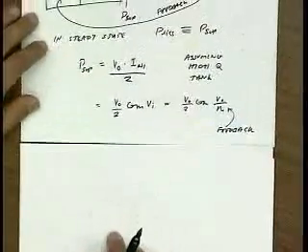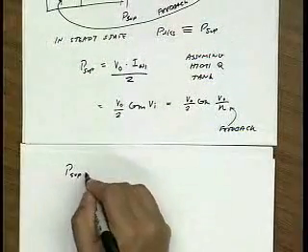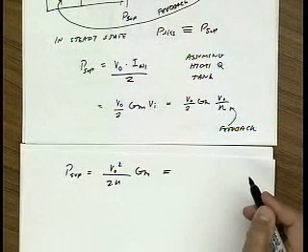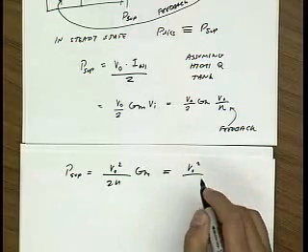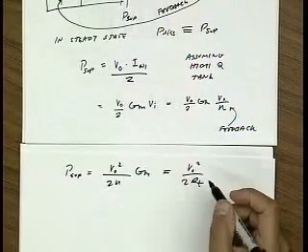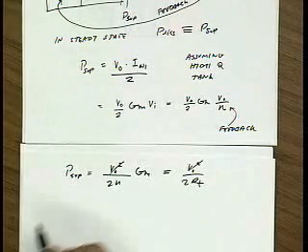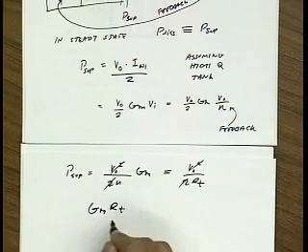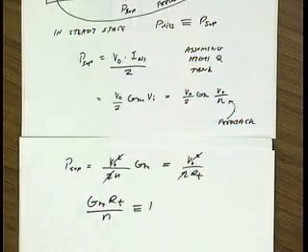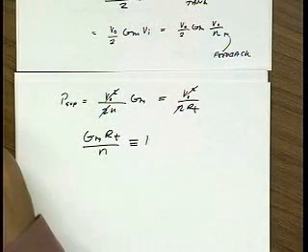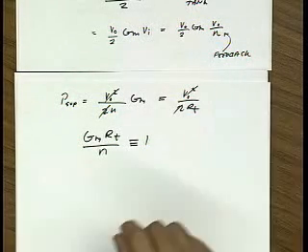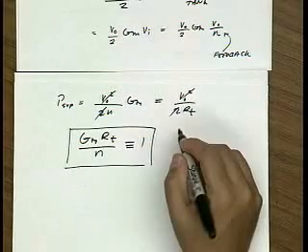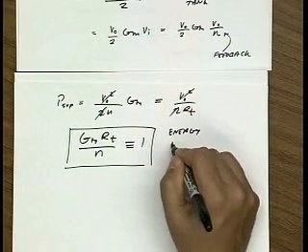All right, well, this is the power. So the power being supplied is V out squared over 2N times GM, and the power being dissipated by the tank is V out squared over 2RT. And so we see that V out drops out, factor of 2 drops out, and we have an equation: GM RT over N is therefore identically equal to 1. And this is the same equation that we derived last lecture, but now through a different perspective. So if this condition is satisfied, then we have energy balance.